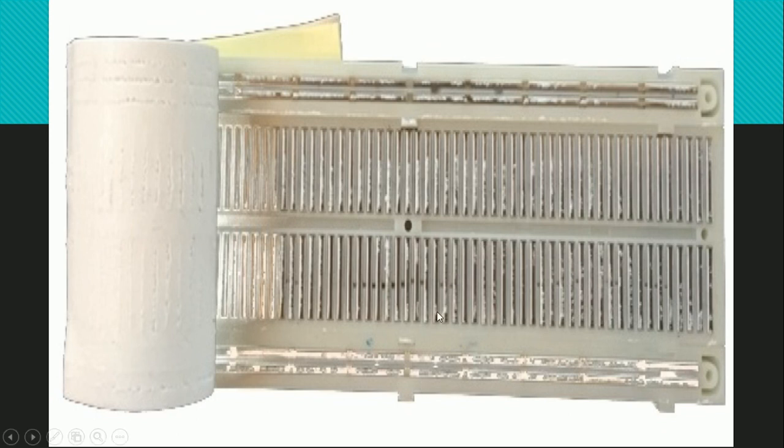this breadboard is different, because there are breadboards that, just like this one, are divided in the middle, so there's no connection. When I connected a power source to this point and the components to the other side, the power source and the ground will not flow, because it is divided in the middle.